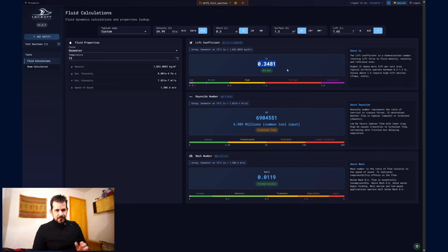For you to have an idea, here we have a little scale. The normal range of a CL that's lifting is between 0.1 and 0.8. What we consider a high CL would be between 0.8 and 1.5. We call it extreme. Don't be alarmed by this naming, but between 1.5 and 3, the CL is very, very big. So you have a very big risk of flow separation.